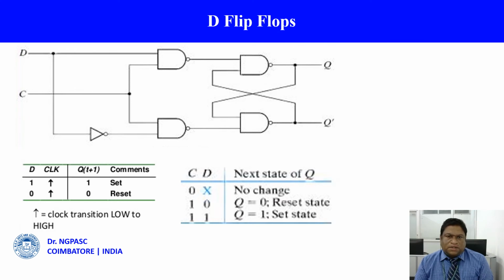Whenever there is a D value of 1, immediately a complementary input goes into the system, so that you give an input as either 0 1 or 1 0. The first input is given as 1, then the other automatically becomes 0, so that we get output as 1. Then we give a D value again, the second value is 0, then automatically the value going to the second gate is 1.